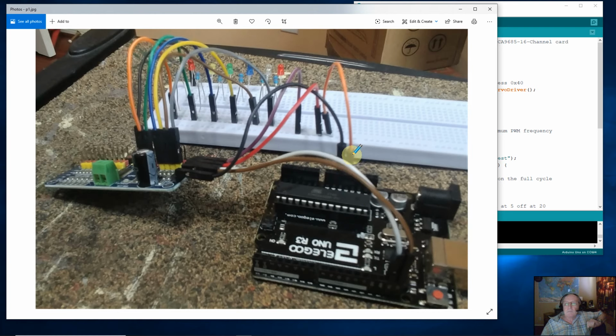So here we have 5 volts coming out to the breadboard, and we have 2 wires jumpered in here coming out to the module. Okay, and just keep these 2 wires in mind here, that they're being sourced from the same 5-volt output pin on the card. And in the next picture or two, we'll go over what they're doing for us.